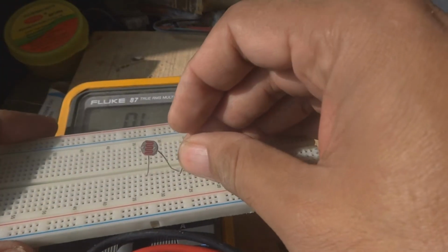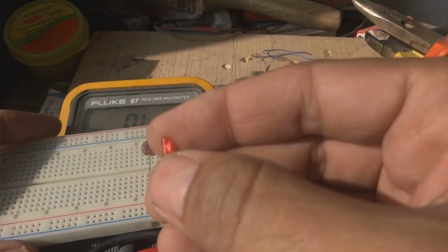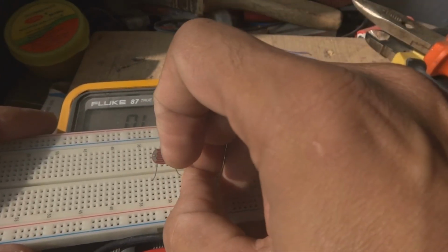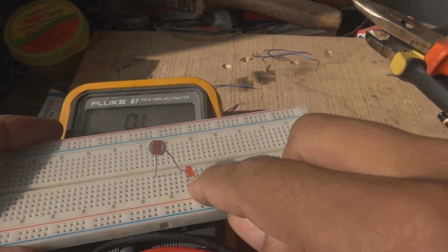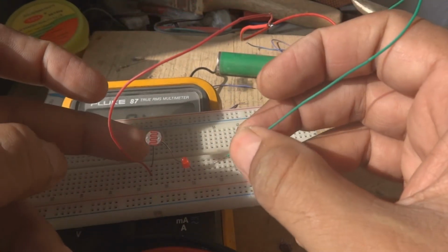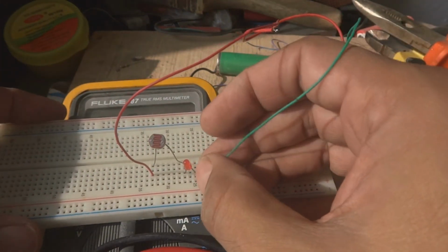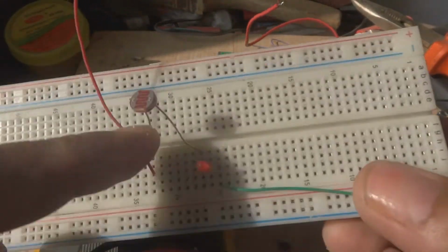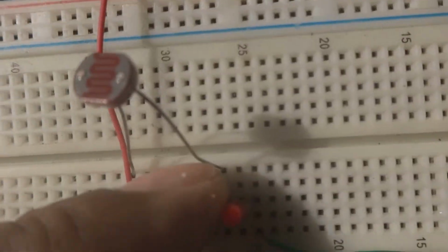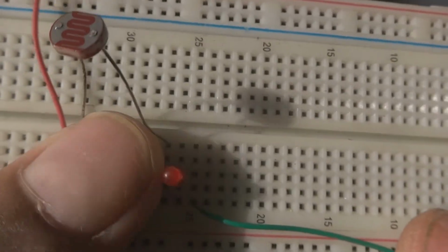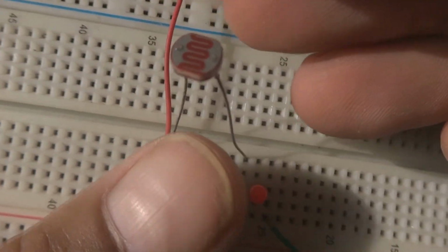We are going to put one LED with it. We have a very small LED. The anode side I am connecting to the LDR, and the cathode side is open. Now we need a battery or some source to power it up. So we are going to connect the negative and positive of a 3.7 volt battery, and here is this connection. You can see this light is lighting now. The reason is this LDR is in the light, very small light. You can see this is lighting up. Now as you can see, this is in light.